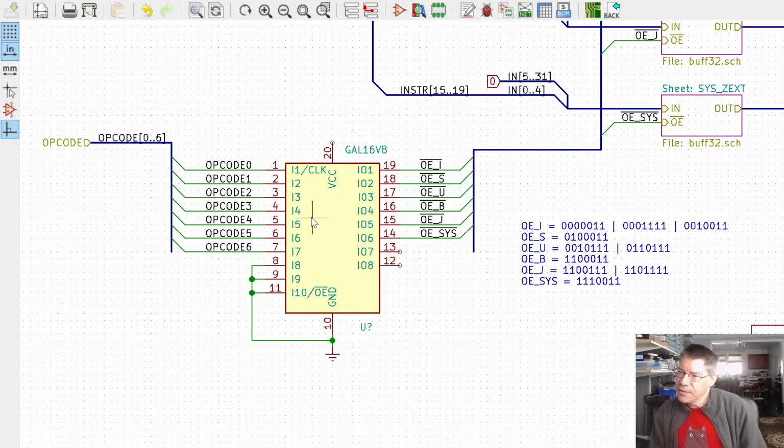Can't you have one selector active and simply ignore the immediate bus? At least it won't be Z. No, because in the circuit, the immediate bus does go somewhere. It may go to a multiplexer, or another multiplexer where the immediate value is simply not selected, in which case you would say, well, then why does the immediate bus even matter? Again, it goes to the input of a chip somewhere. And the chips respond very poorly if their inputs are high impedance, which is why you always want a pull up or a pull down.